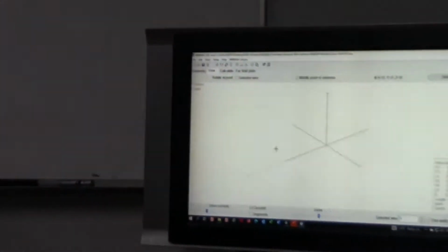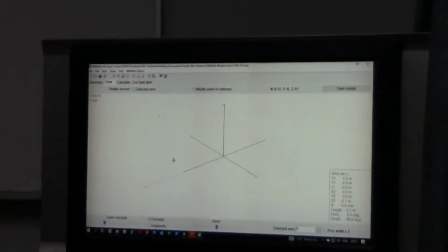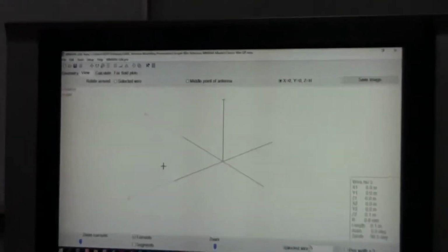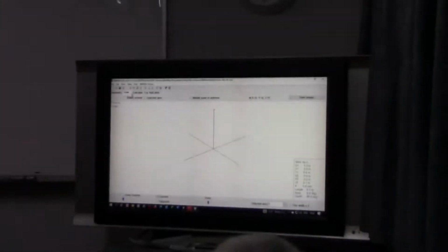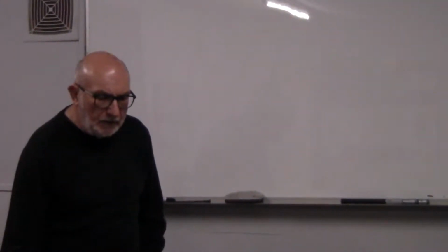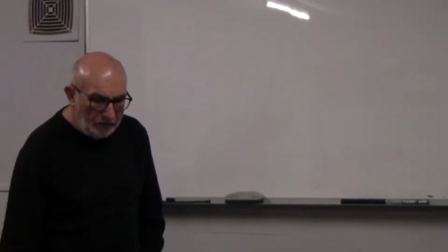And it's a classic quarter wave ground plane. Could be for any band. These dimensions are for 40 metres. You will do the same thing for 2 metres. Look around, you'll probably see VHF ground planes that look just like this. Okay, so here it is. Let's calculate it. 7.15. Here we go.